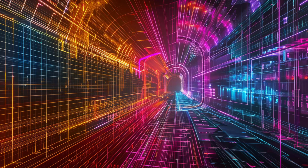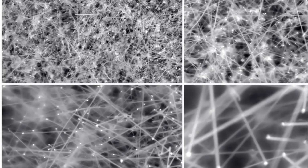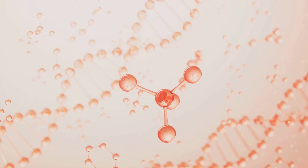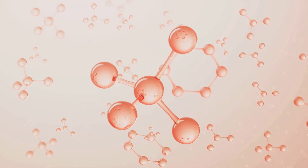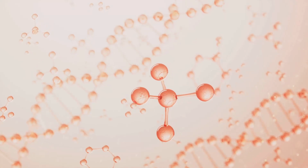Creating these one-dimensional nanostructures is a feat of engineering in itself. So, how is it done? There are two primary approaches, bottom-up and top-down. In the bottom-up approach, we build the nanostructures atom by atom or molecule by molecule. It's like building a Lego tower by stacking one block on top of another. Techniques such as chemical vapor deposition, template-assisted growth, and molecular beam epitaxy fall under this category.